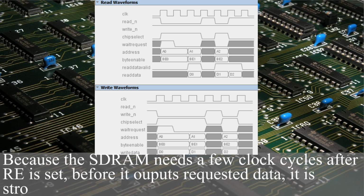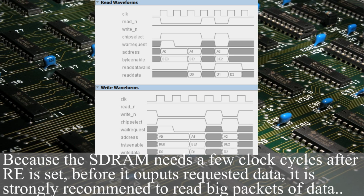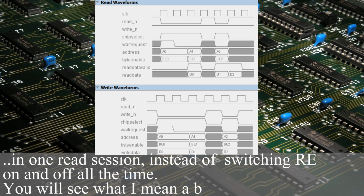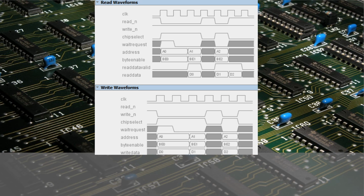Because the SDRAM needs a few clock cycles after read enable is set before it outputs requested data, it is strongly recommended to read big packets of data in one read session, instead of switching read enable on and off all the time. You will see what I mean a bit later.